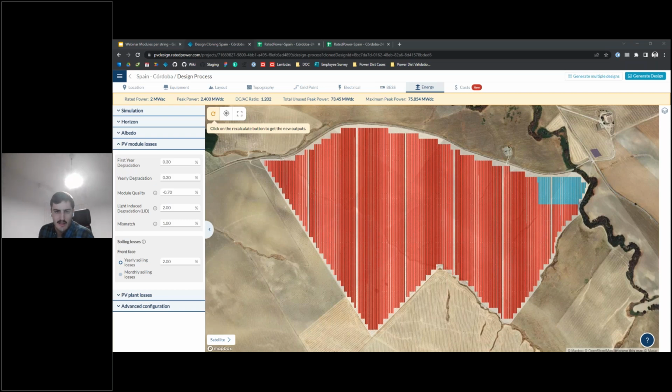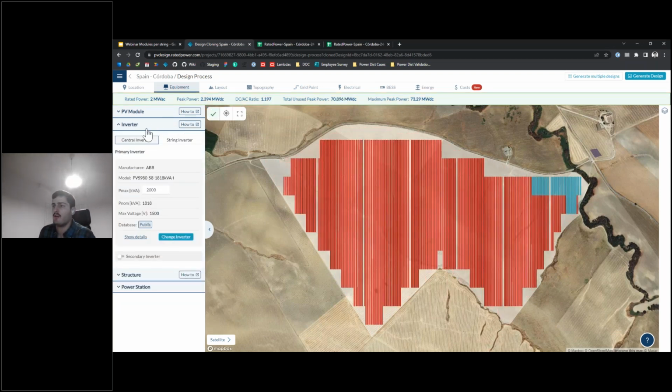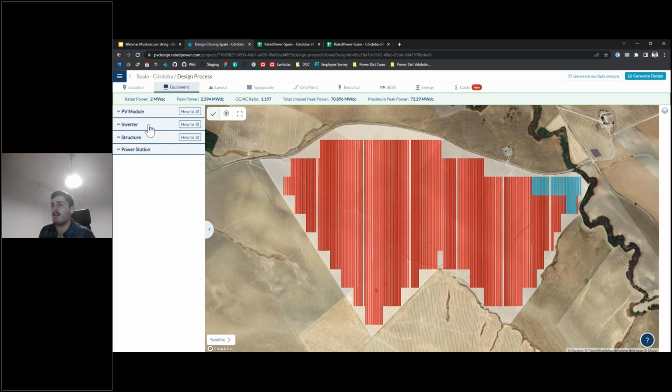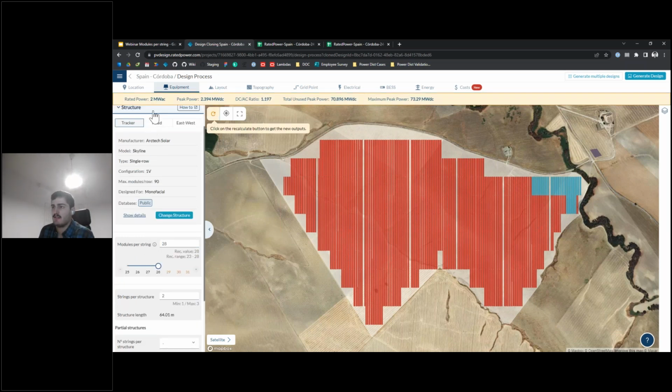So, okay, also Manasa is asking if the inverter has 2 MPPTs, if we can connect 4 strings using a Y cable. Okay, so this is one case that we can use. For example, let's say we have 2 strings per structure in this case.